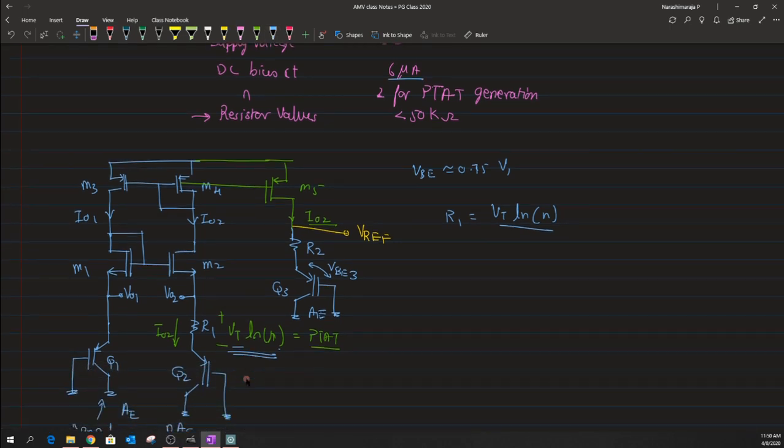and the current flowing through IO2 was given in the spec, equal to 6 microamperes, which is just IO2, or in general I naught. When we plug in those quantities, you would end up with a value equal to 3 kilo ohm. You can verify it by plugging in those values and checking whether you get the same answer. I'm just writing the final value here. Next we need to evaluate the value of R2.